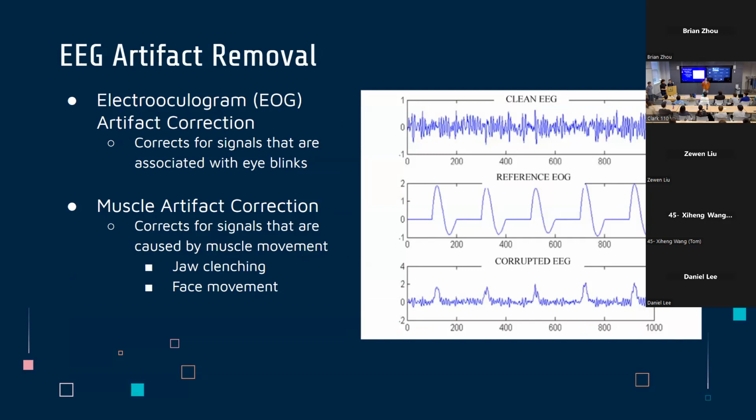When it comes to EEG, there are also a lot of artifacts. One con about EEG is that the signal to noise ratio is relatively low, so the data that you're getting isn't necessarily very good. For example, EEGs can detect eye blinks, and you don't necessarily want that. If you want to detect eye blinks, that's really good. But say you just want to assess cognitive function while they're doing a particular task, you need to correct for eye blinks, because you don't want to say activity is happening when it's not really brain activity, it's muscle activity from the eye.